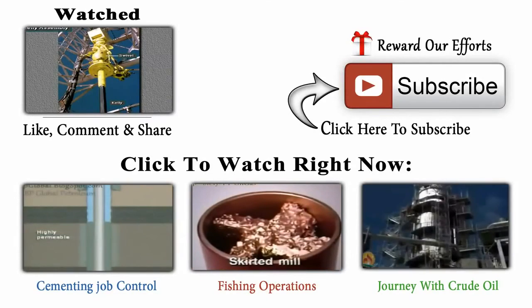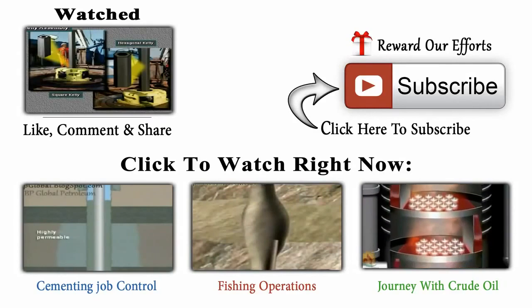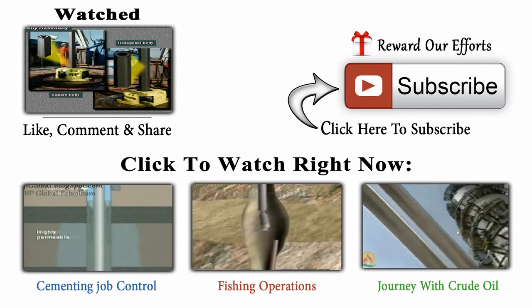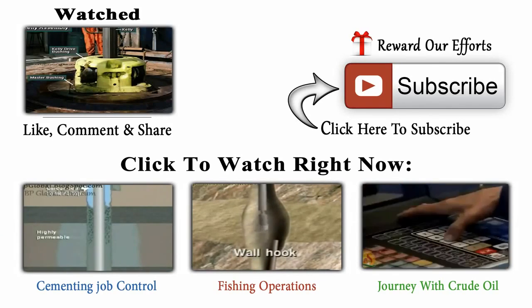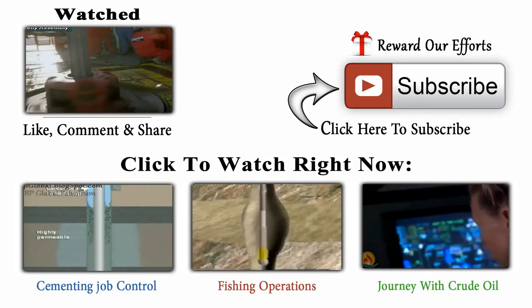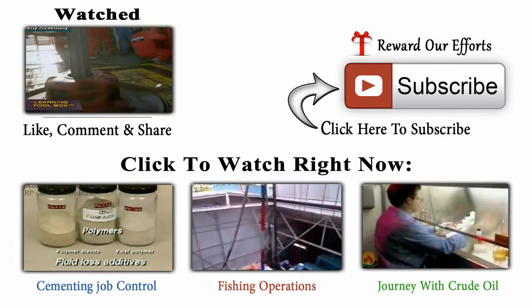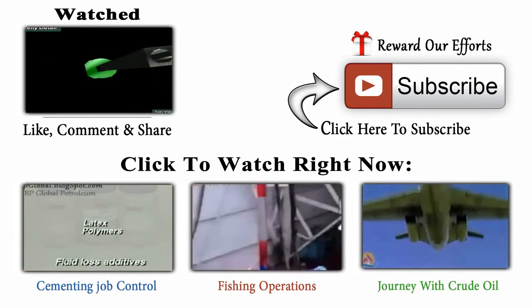Crew members make up the Kelly to the swivel stem. The Kelly has either 4 or 6 sides and passes through a 4 or 6-sided opening in the Kelly drive bushing. The Kelly drive bushing mates with the master bushing. So, when the machinery inside the rotary table rotates the master bushing, the Kelly drive bushing rotates the Kelly and attached drill string and bit. The Kelly is flat-sided.